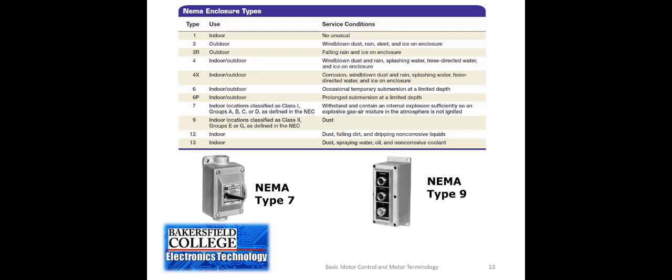explosive particles. So, for example, when you're using one of these control circuits in an environment like, let's say, a mill that takes wheat and grinds it down into flour, that flour is such a fine particle and it is flammable that when we have a lot of that dust in the air, a spark could cause an explosion.